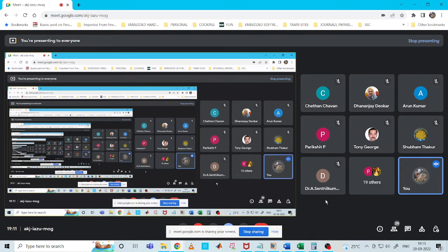See, I'll tell you, these are very easy. The accelerometer portion is very easy. Just think of the algorithm inside. You know, the accelerometer works on a MEMS platform. In that MEMS platform, you have one very small mass, in nano scale. Now there is a change in capacitance there, and that change in capacitance is detected as the acceleration.